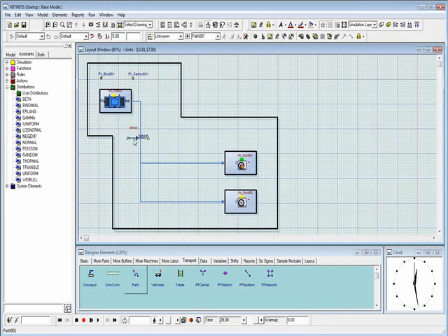We now want to have a path, because of the lines connecting the wrapping and the counting machines, we want the part to actually move along that line as opposed to a straight line between the two. So using the curved path box, we are just going to create two simple paths from the wrapping machine to each counting machine. So here we're specifying different segment sizes as we create the model. So changing it to 1. Now we'll put a curve in of a radius of 2 with an angle of 90 degrees, and so forth until we've created our first path.